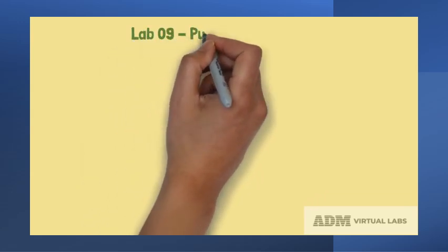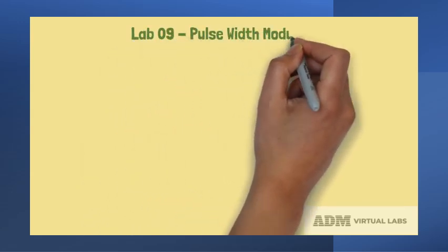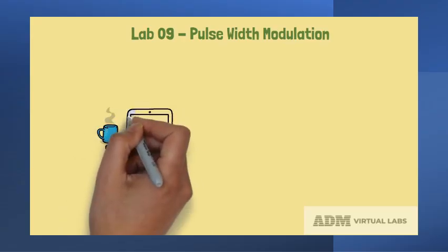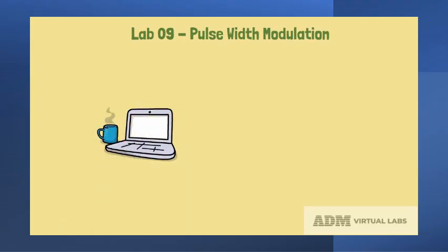Hi, welcome to our 9th training session, where we will demonstrate how to use pulse width modulation technique to create musical scales and simple songs and play it on a speaker.